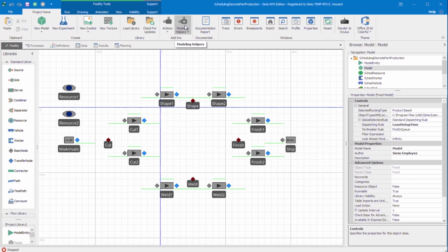A normal Simio install will have no model helpers installed along with it. By selecting something in the drop list, the user enables or disables that add-in for the active model. Once any add-ins have been enabled, that will disable undo and redo. Simio will make sure you know this. Enabled add-ins can optionally add their own properties alongside the model's properties.